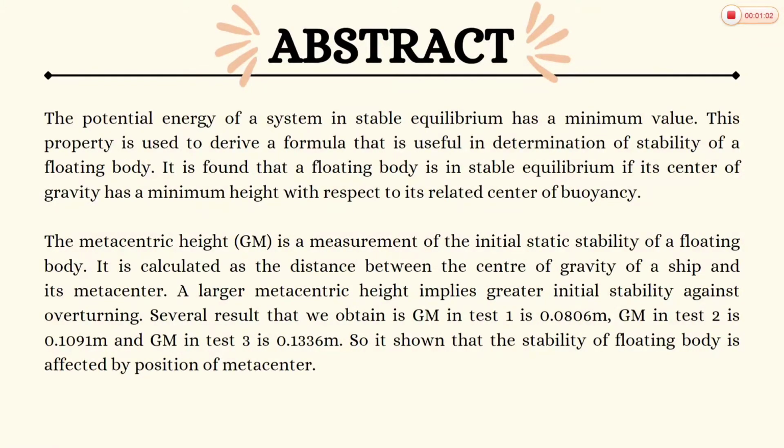So there are several results that we obtain in this experiment, which is the metacentric height in test 1 is 0.0806 meter. The metacentric height in test 2 is 0.1091 meter, and metacentric height in test 3 is 0.1336 meter. So it's shown that the stability of floating body is affected by position of metacenter.